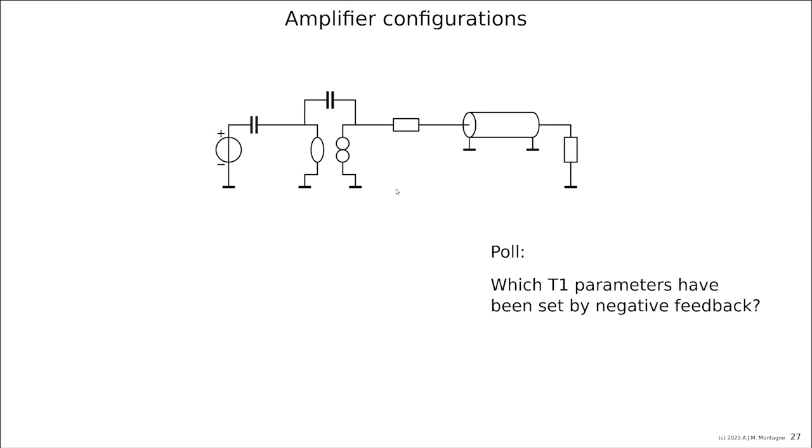The reason for this was that there is no input voltage swing at the input of the antenna, which makes it easy to apply electrostatic discharge components there to protect the input from electrostatic discharge. And those elements often have a nonlinear QV characteristic, so you can say nonlinear capacitance, and in case of voltage you would have voltage swing across them and you would have distortion, but in this case there will be no contribution of distortion of such elements.